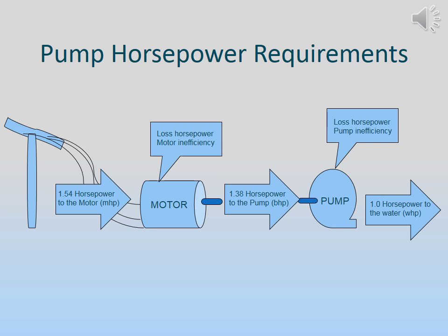The pump has losses. It could be just the nature of the design, internal leakage, or recirculation waste power. As we can see in our pictorial, we only deliver 1 horsepower to the water. This flowchart shows us what goes on from our power company's perspective. This is the power they have to have ready for us. This is the power we are delivering to our water to move it, or air if it is air we're talking about. So it is motor horsepower, brake horsepower, water horsepower.